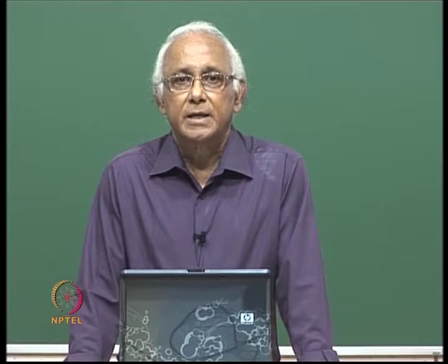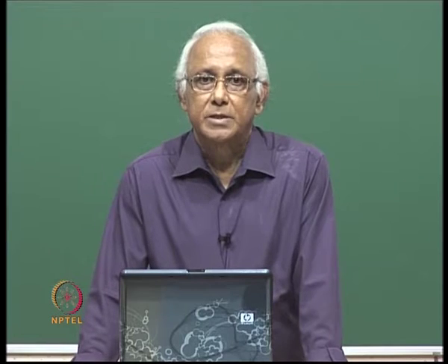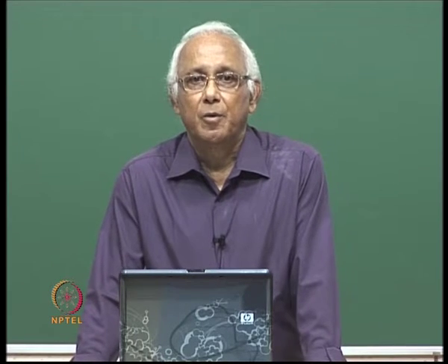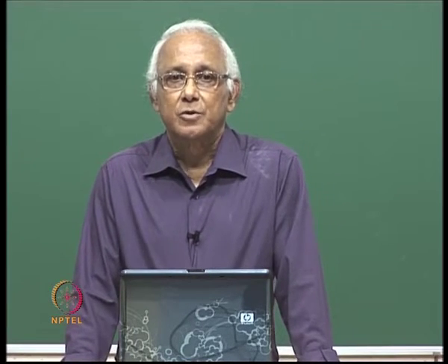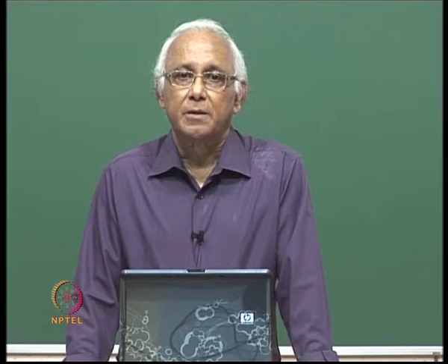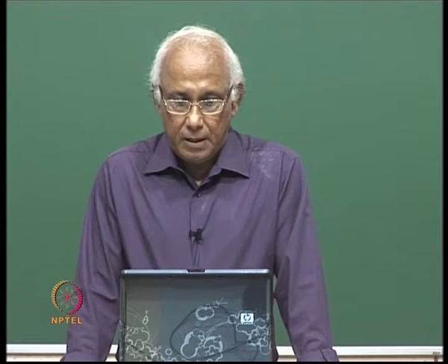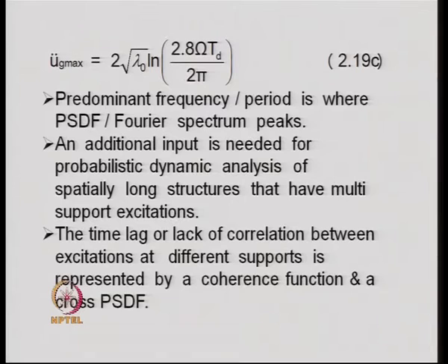In that case, the ground motions are modeled as a stochastic process, and the power spectral density function forms one of the important inputs for considering the earthquake as a random process. We continued with this and saw the definition of the power spectral density function, assuming the ground motion to be a stationary ergodic process.